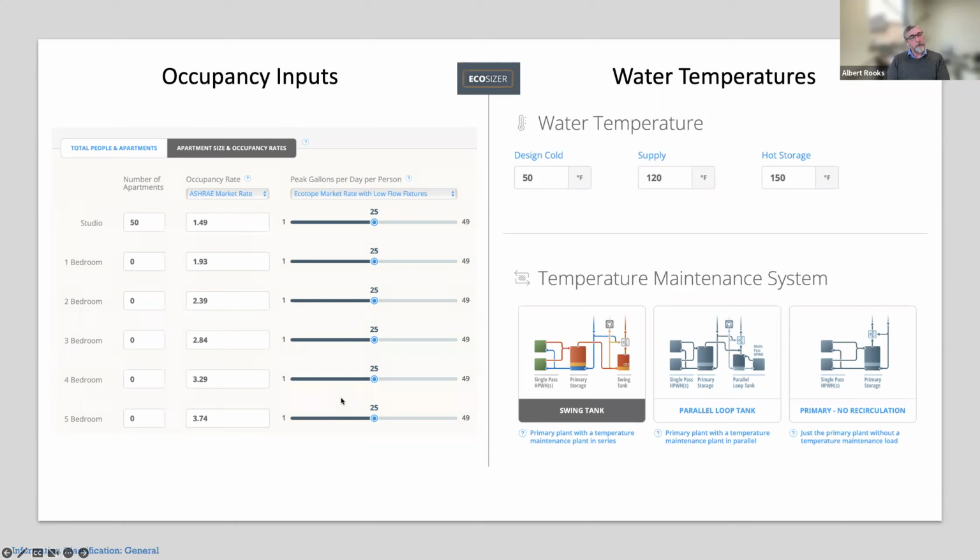So there's a number of choices. And it's super interesting because things are different, and new buildings have low flow fixtures compared to old buildings. So you've got to think about this a little bit. In a new building, there's a drop down where we can select 20 gallons a day. There is a California specification in there that's going to say 30 gallons per day per person. It's a number. We look at our site and we settle on a number.